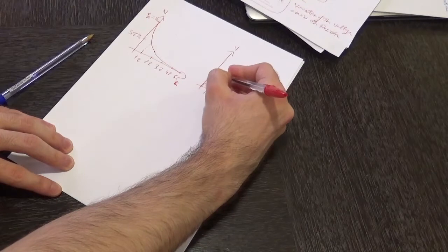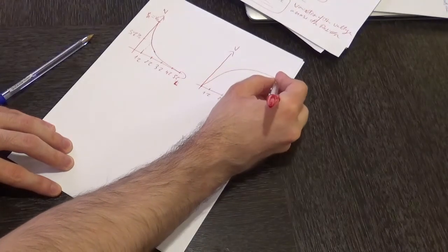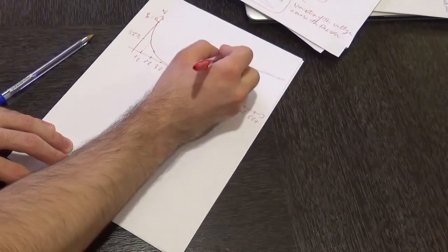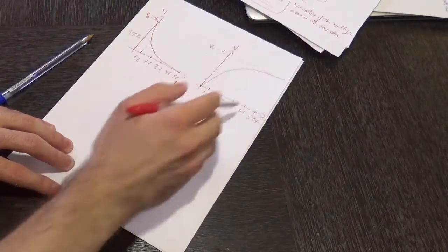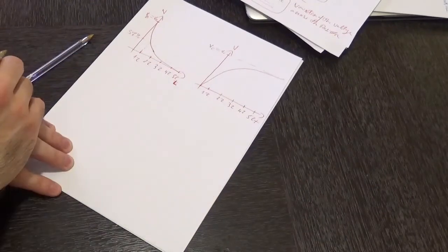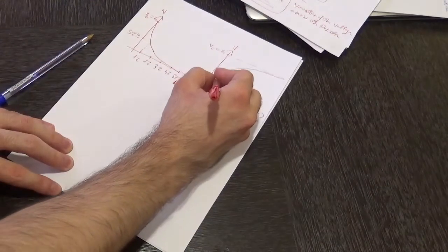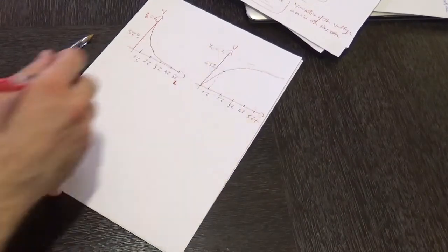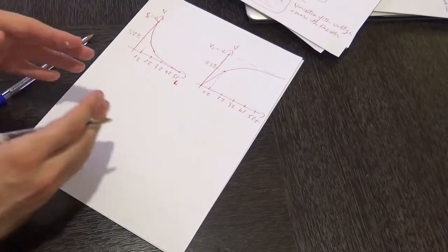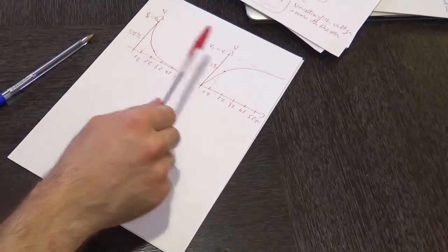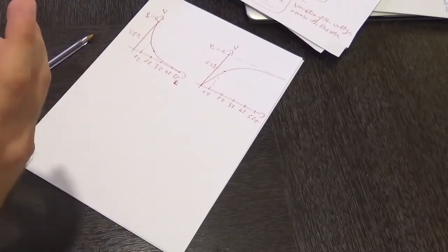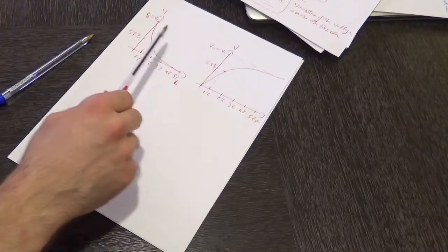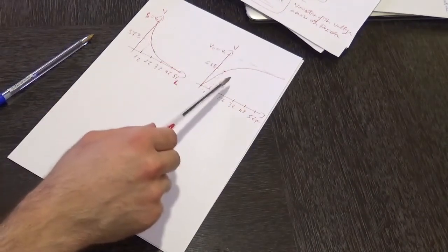So over here we have the following exponential increment until we get to the maximum value across the capacitor, for which Vc is equal to V0 after a time of 5 tau. And after 1 tau we have a charge up of 63% of the maximum value of V0. As we can see, the voltages across the resistor and the capacitor behave in an opposite manner to each other. Over here we have an exponential decay, over here we have an exponential increase. But in both cases we have an exponential response for the voltages.